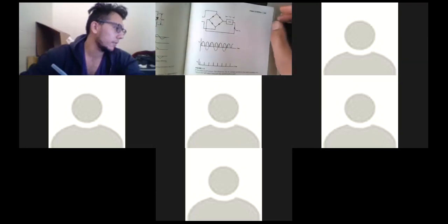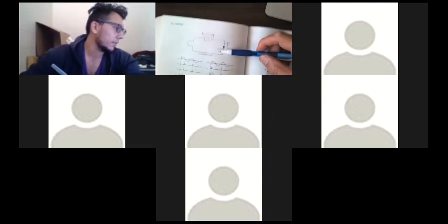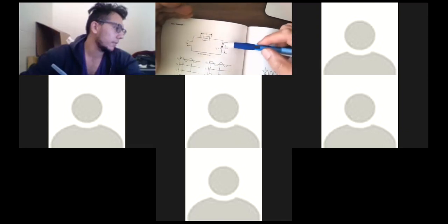So what exactly is the first diode? This is the SCR. It's not like a conventional diode. It has a control terminal. So it's actually a controlled diode. If you remember, I always like to use plumbing to explain electrical. A diode is a one-way valve. So, a one-way switch.